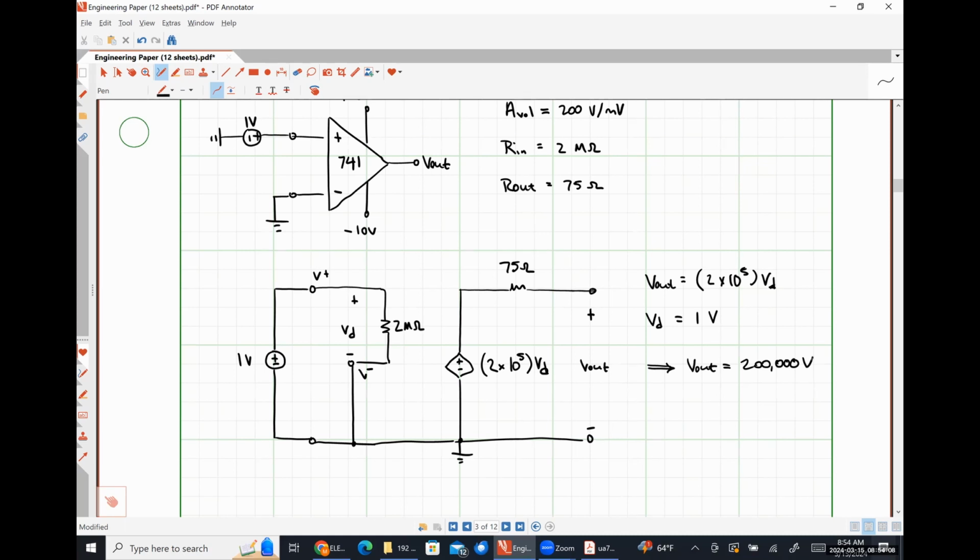Now, technically speaking, that's only true for what are called rail-to-rail op amps, meaning that their output voltage range goes all the way up to VCC plus and all the way down to VCC minus. There are many op amps that don't operate in a rail-to-rail configuration, and so typically there's between 3/4 of a volt and 1 volt of difference. I'm not going to worry about that.